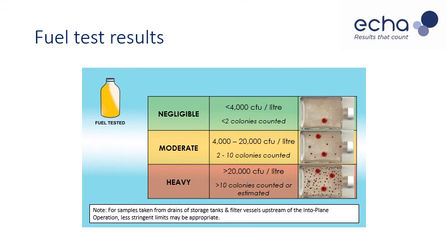Also, there is not always a precise correlation between fuel phase and water phase contamination. If you test both phases, we would generally recommend acting on the test which indicates the highest category of contamination.